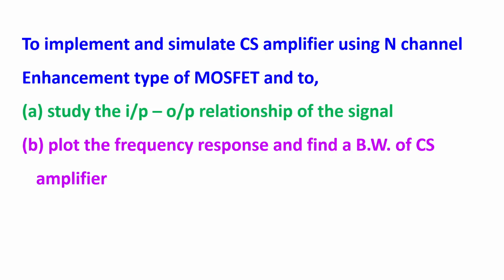In this experiment, we are going to implement and simulate a CS amplifier using an N-channel enhancement type MOSFET and study the input and output relationship of the signal. In the second part, we will plot the frequency response and find the bandwidth of the CS amplifier.